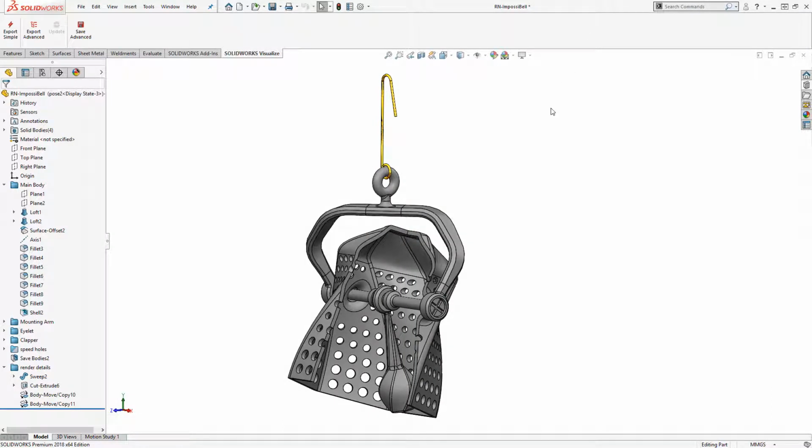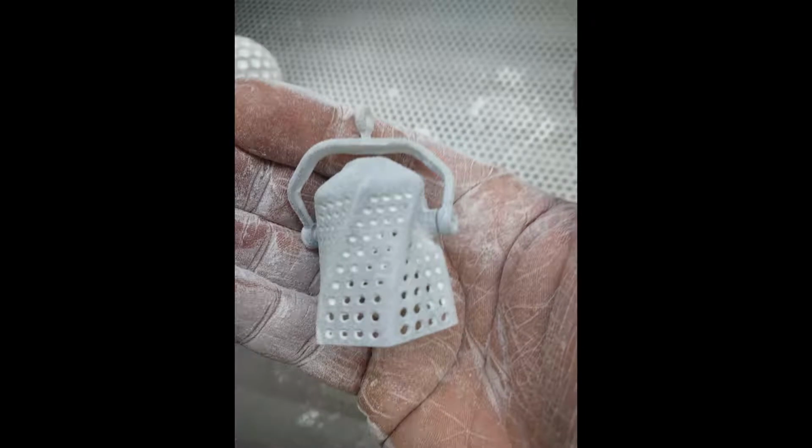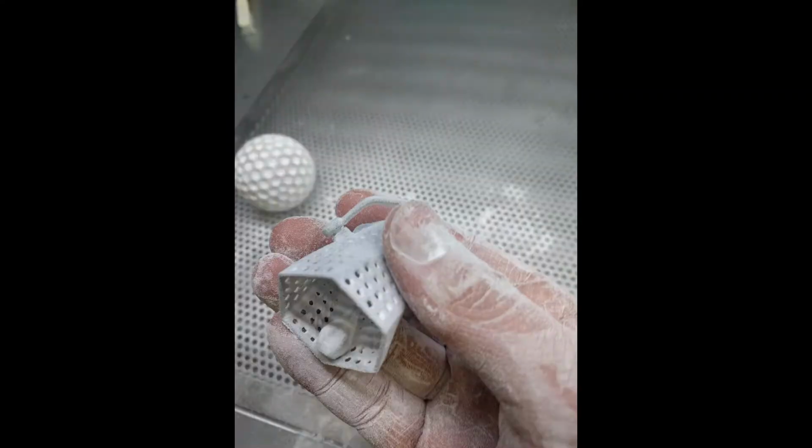And then finally, we'll talk a little bit about the end result. You can see on the screen an image of the part coming straight off the print bed after it was partially post-processed. Some of the powder was blown out of it with compressed air there from our HP 3D printer. And then it's got kind of a light gray natural color by default, and it was dyed to this black color here. And you can see the precision of the detail.